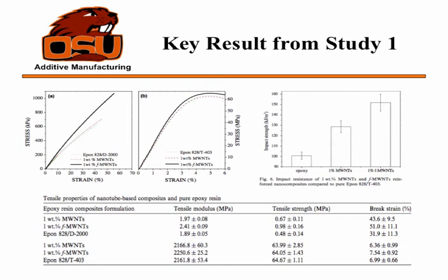They also did an impact strength test to see how impact strength increases for the epoxy without any reinforcement, then with nanotubes, and then with functionalized nanotubes. Functionalized nanotubes means trying to dissolve the carbon nanotubes in an organic solution in order to get a uniform coating so that it disperses well inside the polymer matrix.